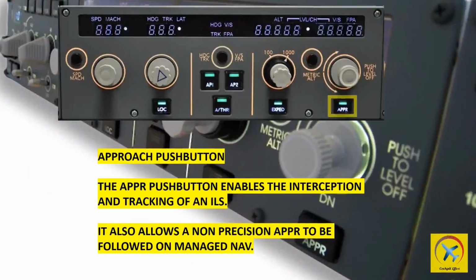The approach button arms, engages, or disengages the following modes. Localizer and glide slope modes. If an ILS approach has been selected via the flight plan or radio NAV page or RMP, it takes a minimum of 3 seconds after arming for the localizer and glide slope to engage in the capture mode. Approach navigation, final, and final approach modes.